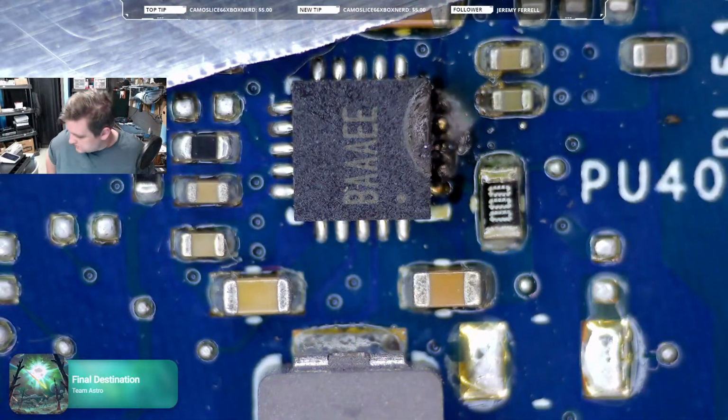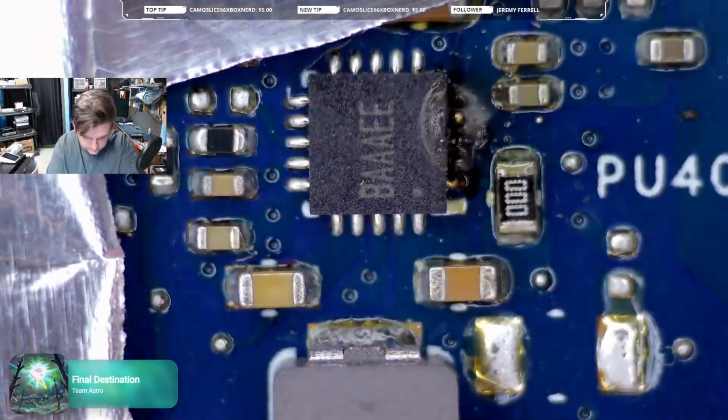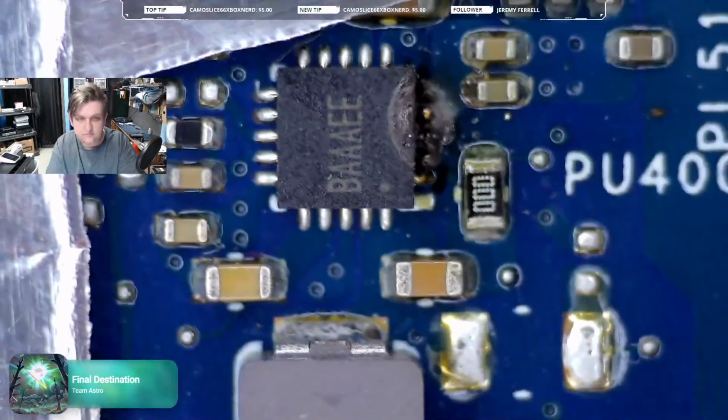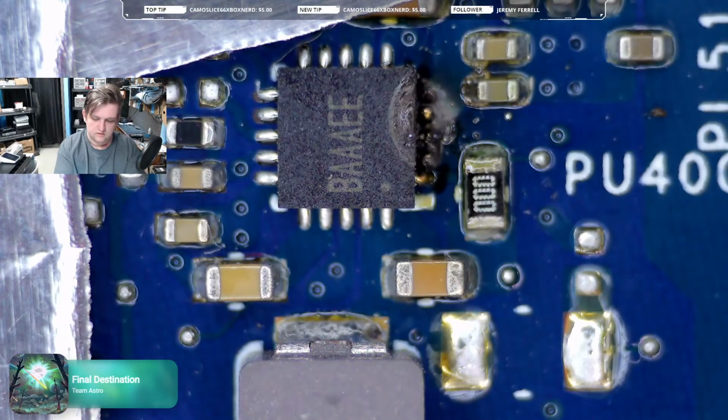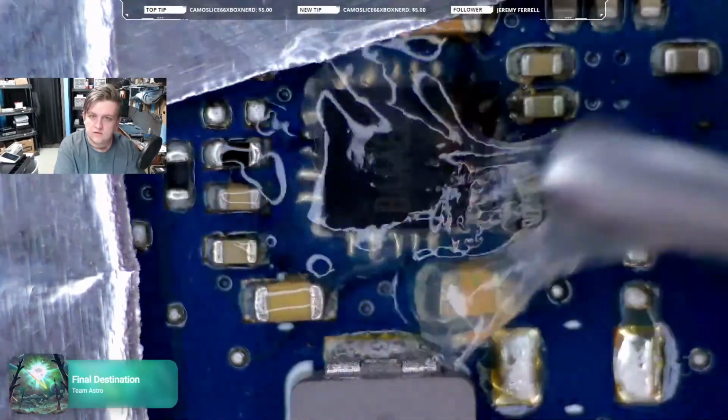Just putting some of my aluminum tape down since I'm right next to the GPU. It's a couple doors down. I don't want it to, I don't really feel like reflowing the chip, heating up anything I don't want to overheat. Not that I suspect I'm going to take a ton of heat to get this chip off anyways, but with burnt out components like that you never know, so just be safe. Go drop a little flux down that guy, get him ready to go.